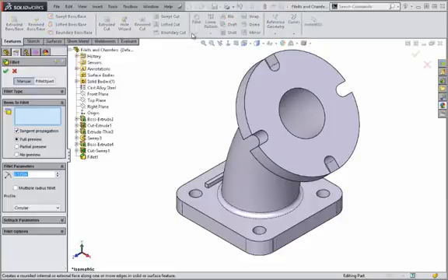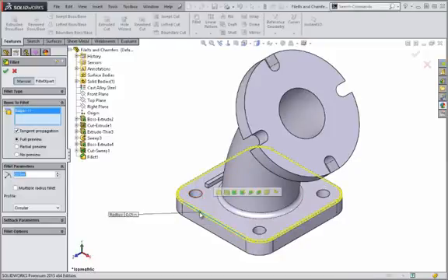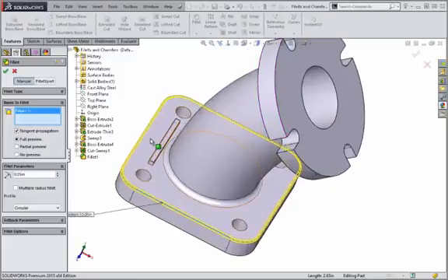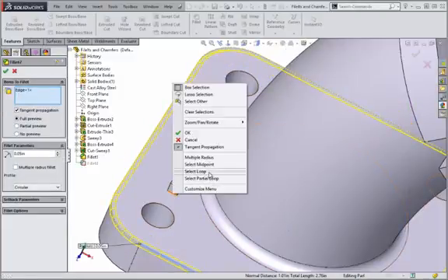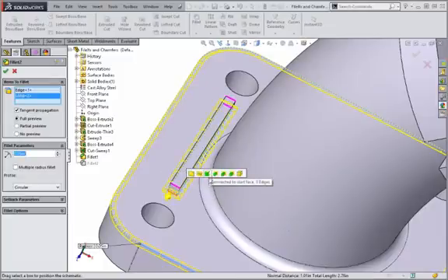I'll go ahead and add one more fillet feature to complete the fillets for our example. Note how tangent edges are automatically selected. And if you want to select a loop of non-tangent edges, right-click and choose Select Loop. Toggling the arrow will switch between the possible loop selections.